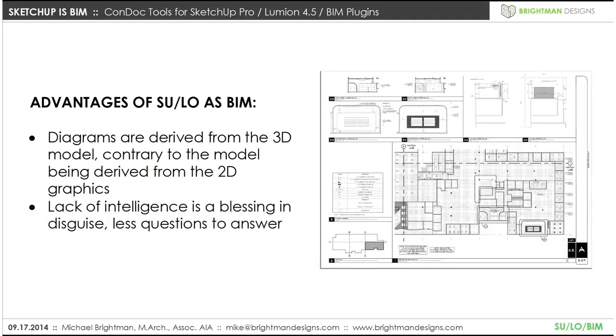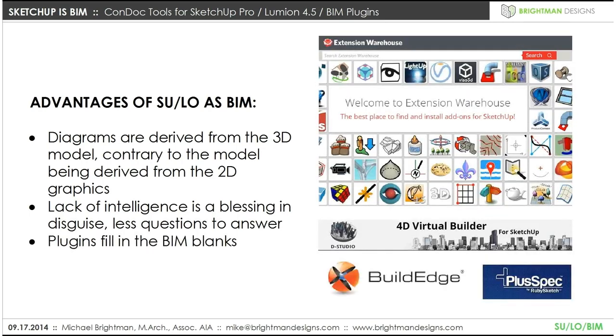This lack of intelligence in SketchUp is truly a blessing in disguise. There's a lot less questions to answer. So as you're going along, you don't have to build a wall type, you just build a wall. You draw a square and push it and pull it. You don't have to answer a ton of questions about what's going in this wall, how are we building it, because probably you don't really know. You just want to kind of get things figured out first. And ultimately, plugins fill in the BIM blanks.